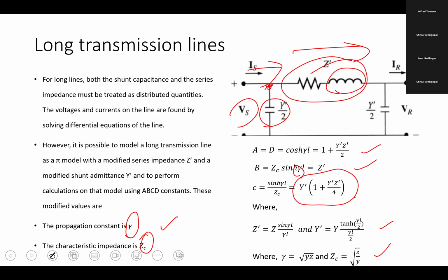So voltage is going fast, current is lagging behind. But at one point of time, they should reach the end within a certain time period. If the current cannot reach and only voltage can reach, then there is a problem. That means the current somewhere fell down, which means there is a disconnection somewhere so that the current cannot travel further.